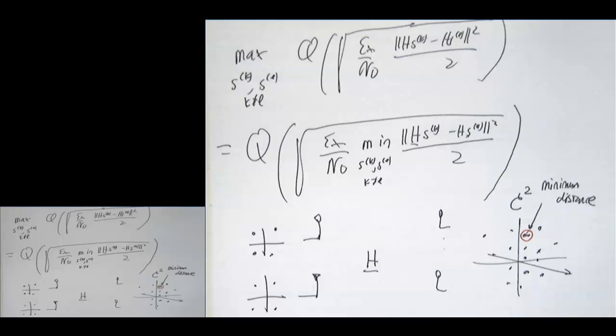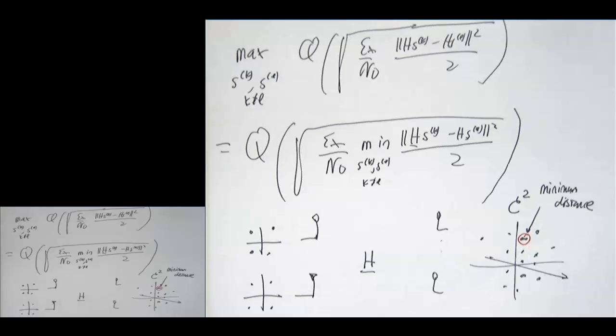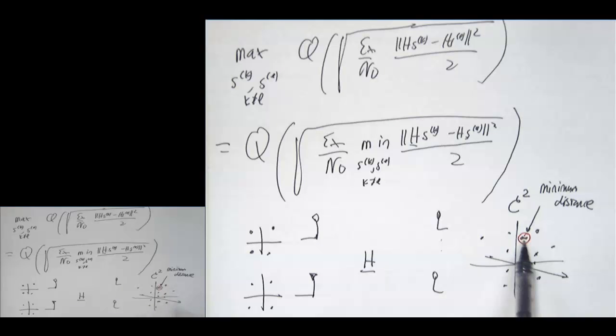It's also one of the reasons that feedback is very important, because you could imagine if you knew that these two constellation points here were really close together, if you knew this h at the transmitter, you would do something to the transmitted signal so that these points either were excluded or were somehow pushed further apart. And you could use generalizations of transmit beamforming to do that. Again, we won't discuss that in the class, but you can see that if you take 381S with me in the spring semester here.